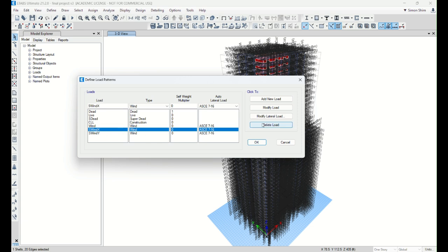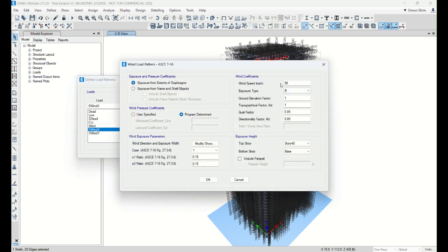Sw, Sy somehow, I guess you set up another service wind load, right? Previously we always used a service wind load, and then later on used a 1.6 load factor. So in the previous version we had a 1.6 service wind, but now in the new version, ASCE 7, right? We're using ultimate wind load. So ultimate wind load means 1.0 times W, ultimate wind. So A plus B, B plus A eventually same, right? I want you to be aware of it.